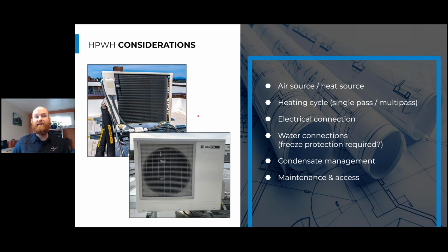And then access to this: if we put these on a penthouse roof where they need a ladder to go up and access, that maintenance procedure probably won't be attended to as frequently as if it was in a much more accessible location. So be conscious about where you put these heat pumps and how you're going to ensure access to them after the project's constructed and the maintenance personnel is doing their routine maintenance procedures.